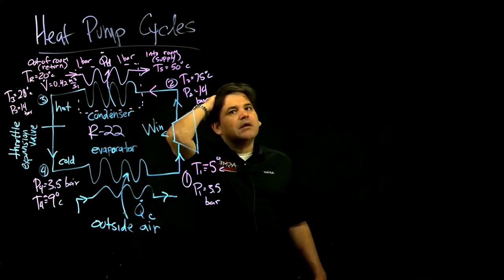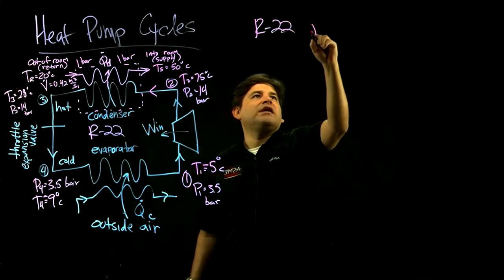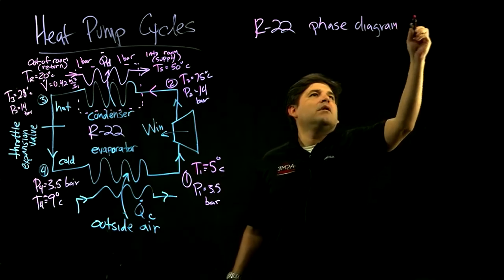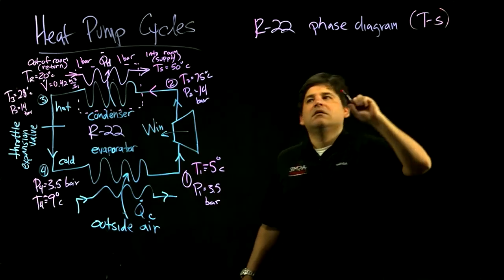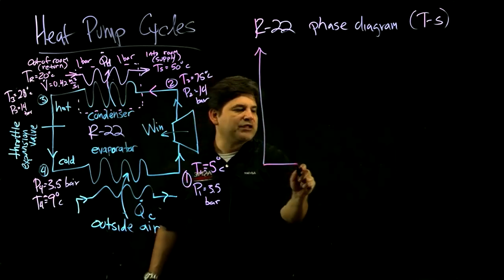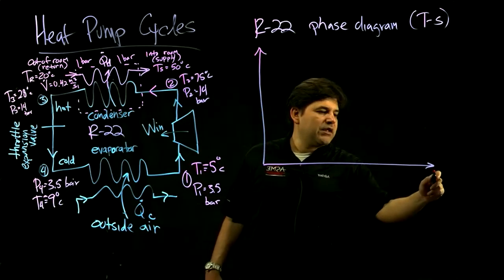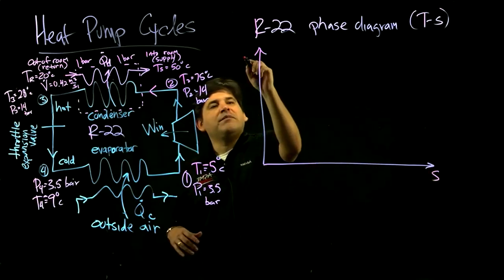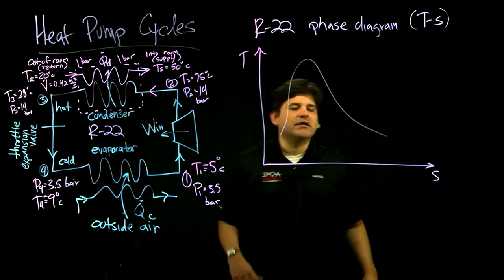Okay, on a phase diagram, what you need is an R22 phase diagram, specifically, or steam tables, and we're going to look at this graphically on a TS diagram. So typical reverse heat engines, whether they're vapor compression for air conditioning, refrigeration, or heat pump, operate on this refrigerant on the saturated liquid vapor dome, meaning that there are some regions of phase change between liquid and vapor.